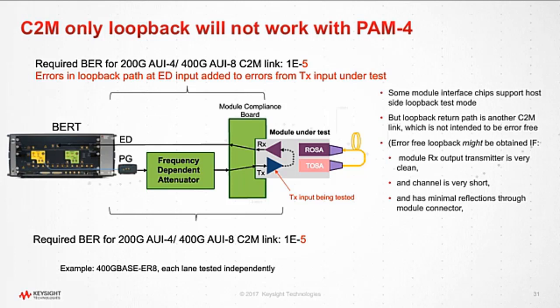And in their testing, they actually didn't have this bundled into the module yet. It was still on an evaluation board. They were able to access this signal with a cable, so they were eliminating that connector and using a cleaner connector, and we were able to squeak by and get it to work. But I suspect in the final module, you might have a problem because of the reflections caused by that connector.